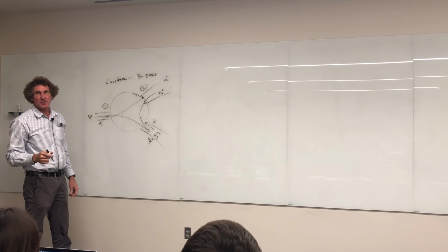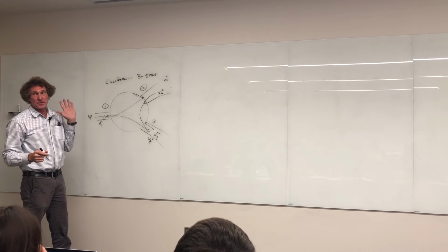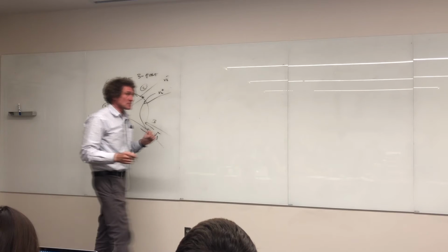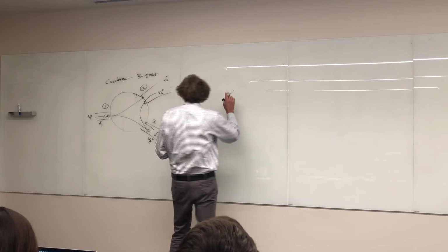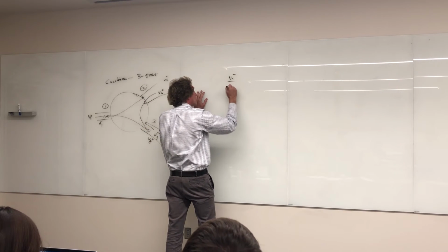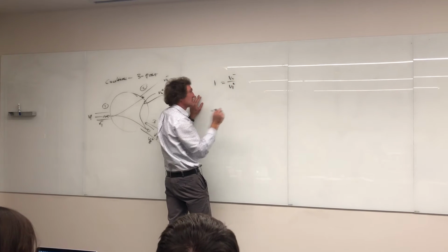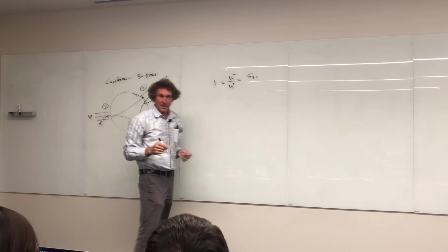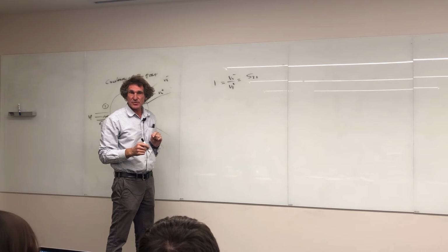These are standard things that are used in radar when you have transceivers, especially when the same horn isn't used for transmission or reception. This is typical. So now, what does the S-parameter matrix look like for this? Let's take a look. We know we're going to have V2 minus over V1 plus equal to 1, right? Well, what is that? That's S2,1, isn't it? 1's going in, 2's coming out. Isn't that right, class? That's S21.